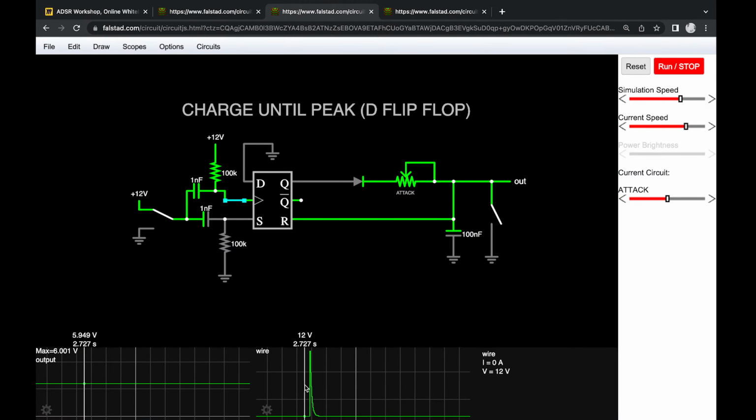So we're getting a spike that goes upwards. Sometimes the simulator is weird. I'm not sure if this would actually also happen in real life. But since it's just a tiny spike, even if it did happen, it wouldn't fry our chip because it's such a short little burst. So that's fine. But we don't really care about an upward spike, right? That's from 12 volts up, the chip is not going to register it, because for the chip to register it, it has to start at 0. It doesn't start at 0, right?